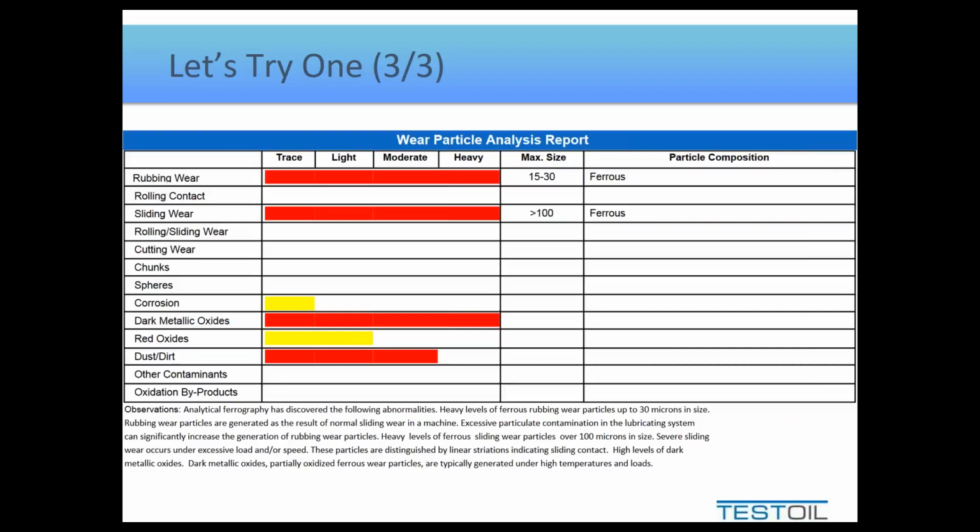And this kind of cascading logic is what we use to interpret the reports, and we decide what we are doing next. So though we had high silicon, particle count, and dust and dirt, we don't necessarily go inspect the breathers or change the oil based on that data. We realize there's another driver to this, and it could be viscosity related due to the water content, and it definitely is wear related based on the other data.